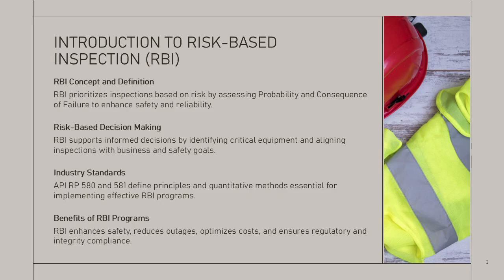Risk-based inspection, RBI, is a structured and systematic methodology used to prioritize inspection activities based on the risk posed by equipment failure. As defined in API Recommended Practice 580 and 581, RBI integrates principles of risk management, mechanical integrity, and inspection planning to improve safety, reliability, and cost-effectiveness in operating facilities.